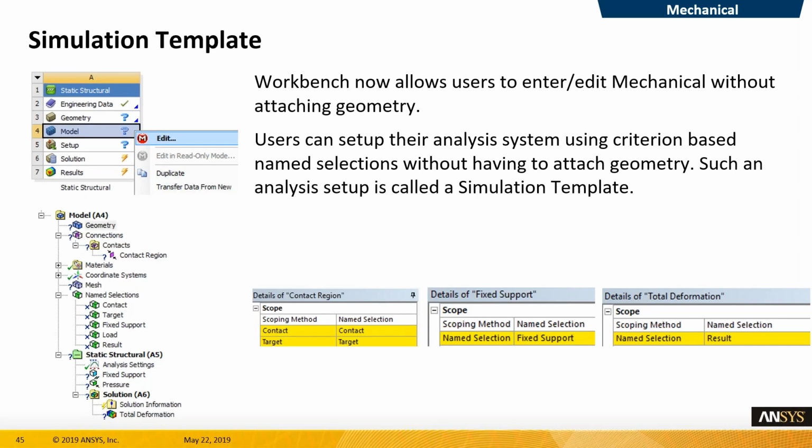As I said before, this now allows us to make a simulation template. So you could store a common template for standard simulations. This has been a really big lack for ANSYS, that you needed to do either a script or a journal file or something in APDL, but now you can actually do the whole setup: make the coordinate systems, named selections, loading scenarios, bond conditions, etc., outputs in a template file.